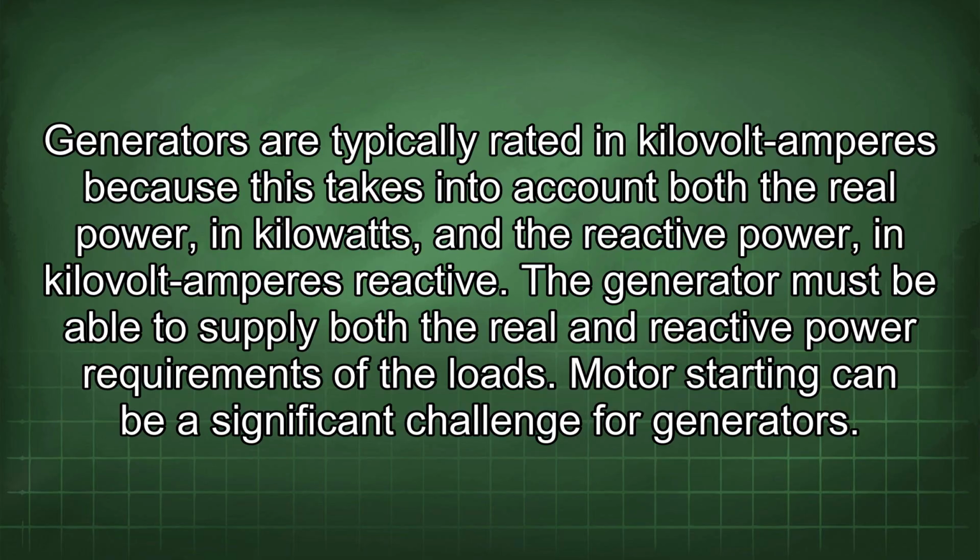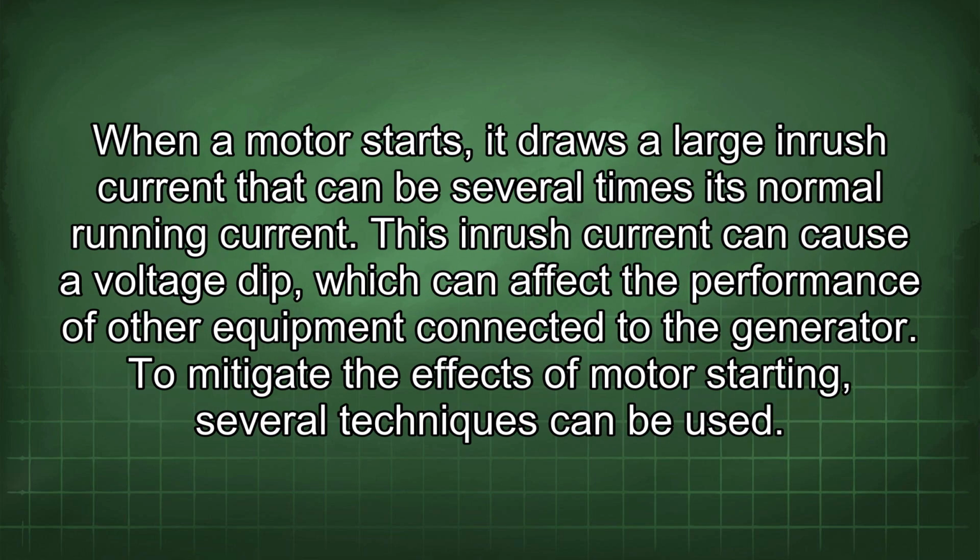Motor starting can be a significant challenge for generators. When a motor starts, it draws a large inrush current that can be several times its normal running current. This inrush current can cause a voltage dip, which can affect the performance of other equipment connected to the generator.